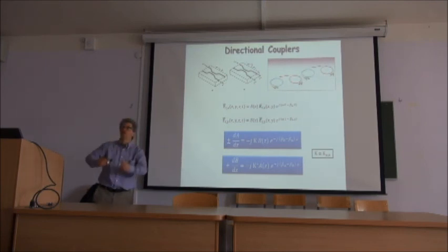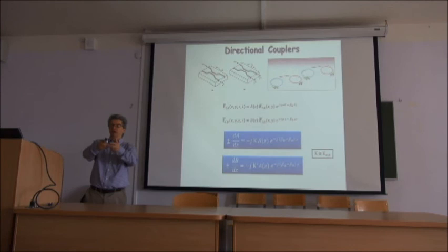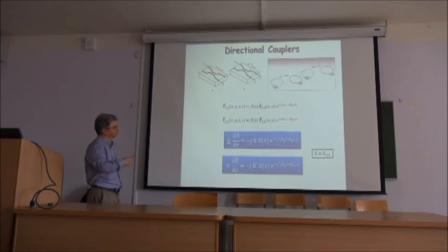You're taking two fibers, you twist them, and you actually put a torch and pull, and you get the cores close to each other, and that also will couple modes there, and that will provide the basis for transferring power from one channel to another.